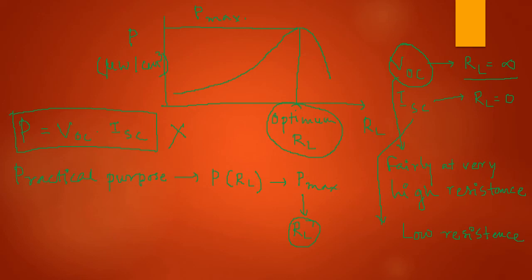However, this peak output power is still based on the maximum voltage generated in a cycle. As I told you, if you are calculating the peak value of the power, it comes from the peak value of the voltage, and it is an instantaneous power. It is giving you the instantaneous power, but this is not the actual power. So power should be measured at a particular value of the RL, using the rectifier circuit as well as the capacitor circuit and the load resistance that we have seen earlier. Okay, so that is how it should be measured.